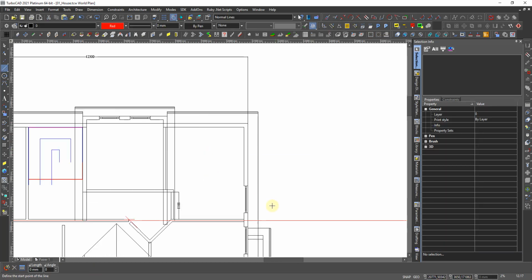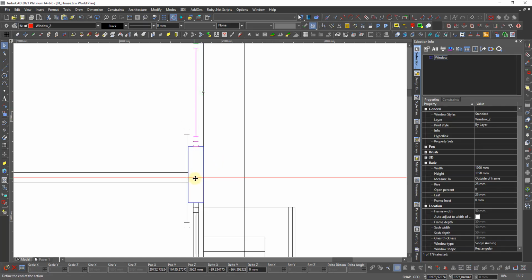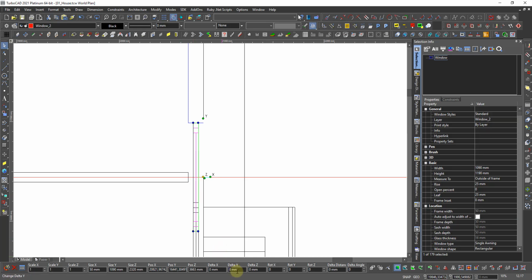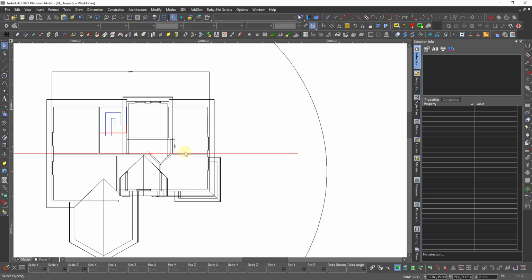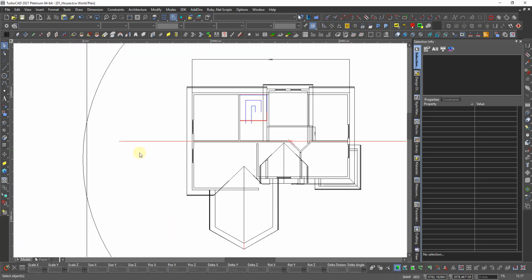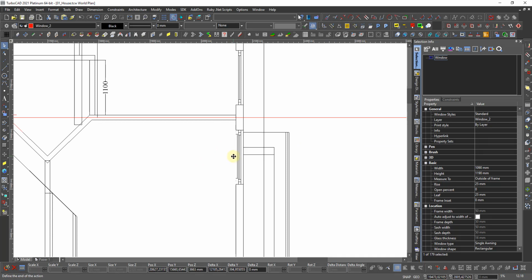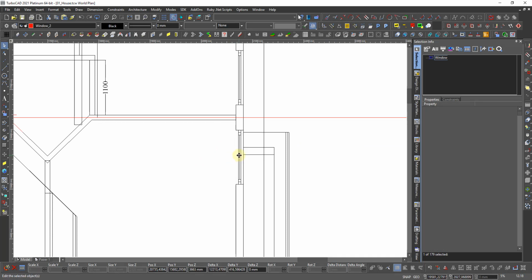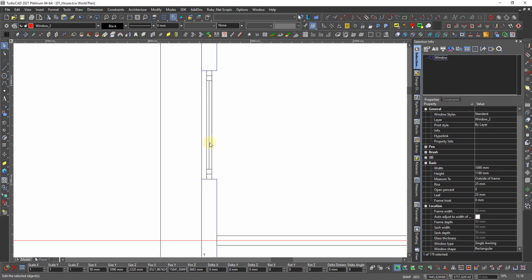Then we have the window up here, and I take that window and go to J, and then I take it up again, delta Y, 800, wasn't it? Yeah, 800. There. Then it's standing in the middle. Because the window is linked to the wall, I don't need to measure this one. So I take that window, and I say it should stand in the middle of this window on M. But because it's linked, it's jumping back again to the wall where it is inserted.